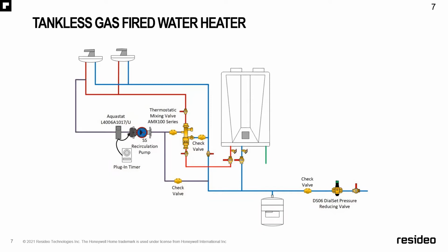You're maximizing the output of that tankless water heater to its fullest. So if you have like a 75,000 BTU tankless water heater, and you have it set to hit 160 degrees, well, it's going to ramp up to get that 160 degrees to cover the demand. And then you have your mixing valve to mix it back down to 120 at a safe temperature. So this is one system that we would see, and it's actually more commonly being used in the marketplace.